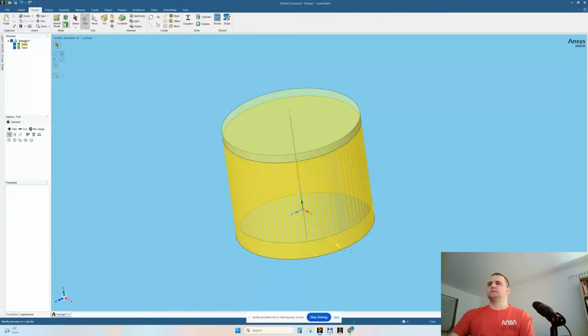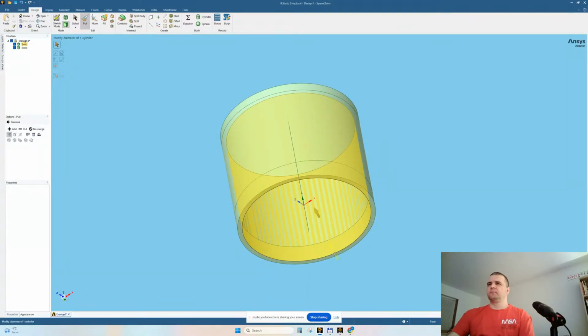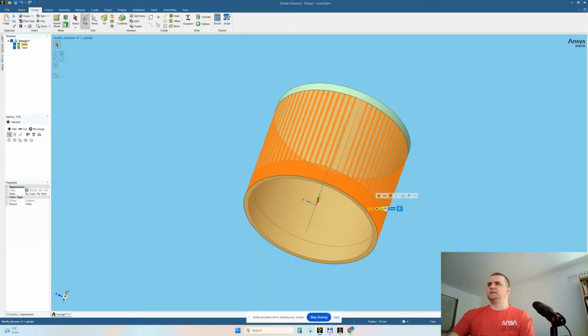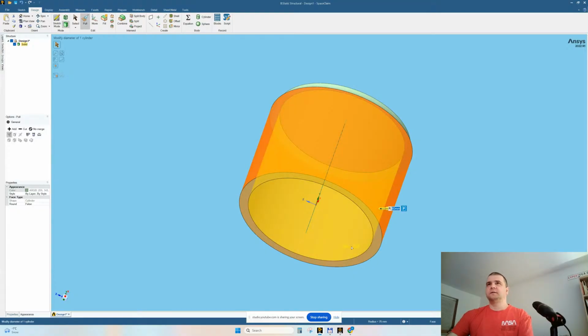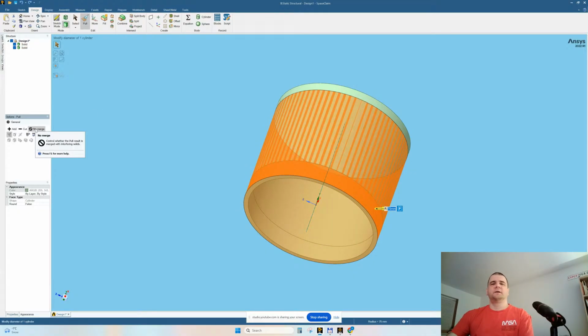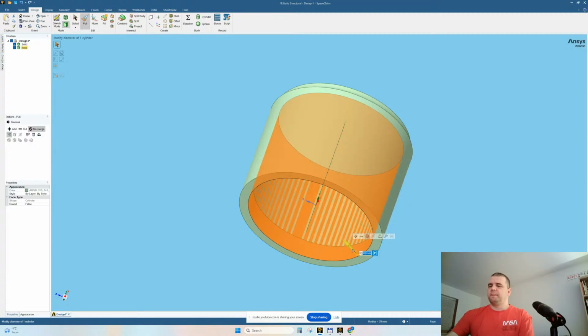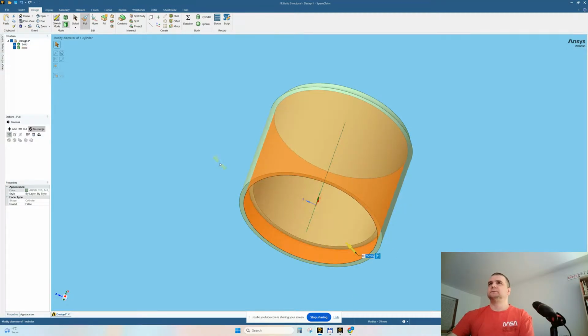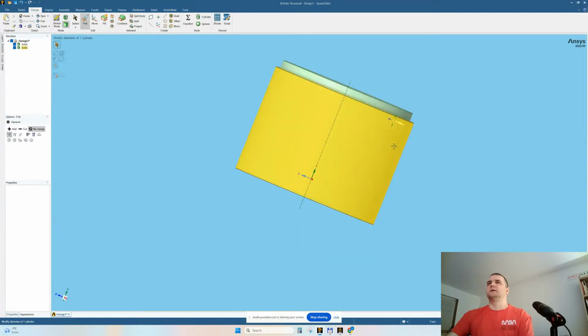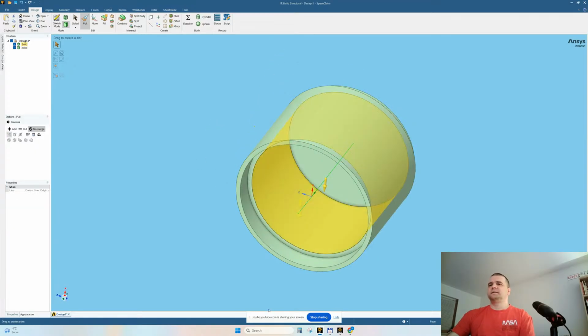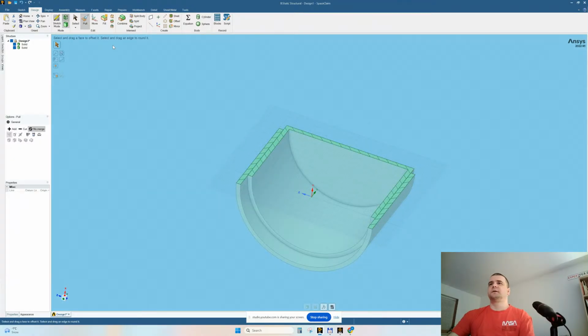And of course, different diameters, yes? So let's make the outer cylinder how much? Should we displace with, yeah, 80? And here inside, of course, I need to select here no merge, all right? Or else by default it will merge with the other parts. So 80 here, and maybe 75. Does it work? Yes, it kind of works. Let's go in the section view to see how things are. Look, something like this. All right.